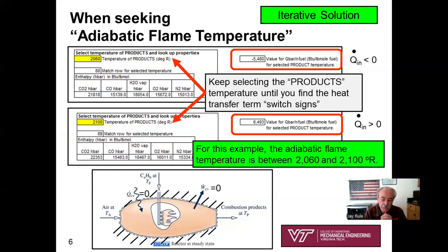So in the real world, that would give you an estimate for T sub H, and that can help you in your engineering analysis determining the maximum possible thermal efficiency of a proposed cycle. It can also help when you're designing equipment. It helps you design for a certain maximum temperature in the combustion chamber.